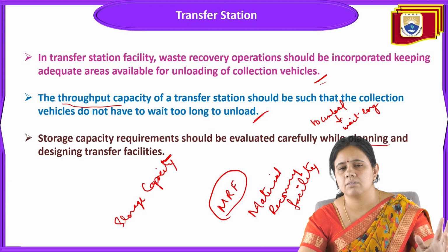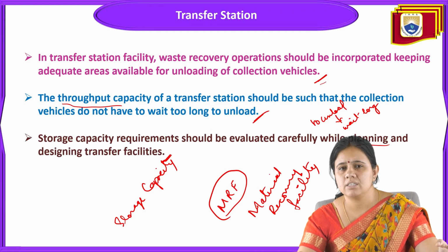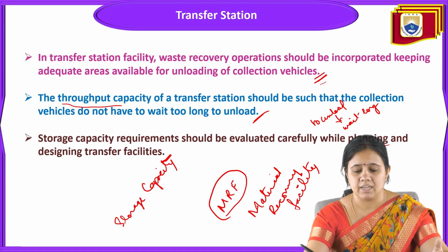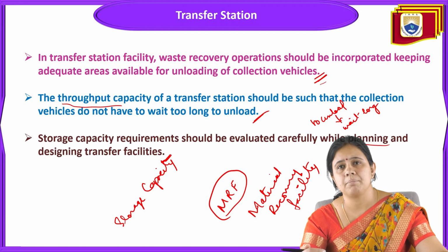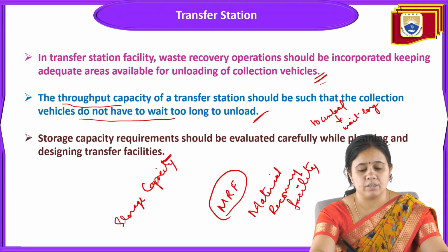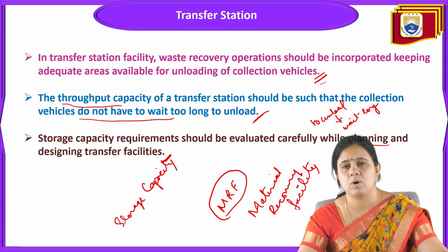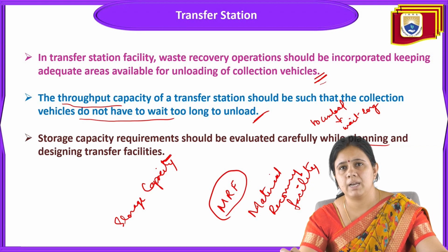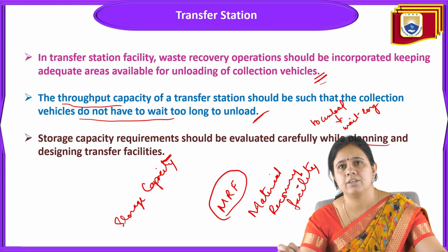So for the transfer station, there are three points. First, the waste recovery operation related to the transfer station should be incorporated, keeping adequate area available for loading and unloading of collection vehicles. Next, the throughput capacity of the transfer station should be such that the collection vehicle does not have to wait too long to unload.